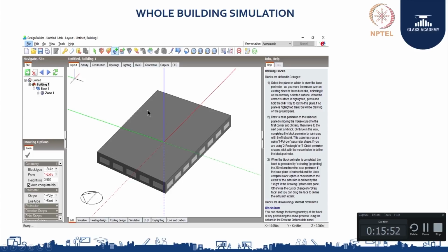So, here I have modeled a small case study building. Here in this building you can see that the windows are default model, etc. After this is done, you need to mark which side is the north, because that is also important. The orientation of your building is one of the most important criteria you need to consider in the start of the design.